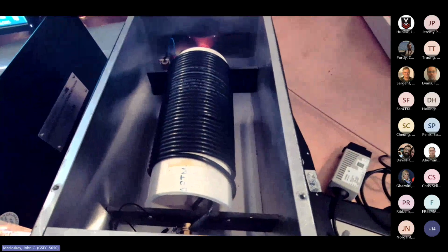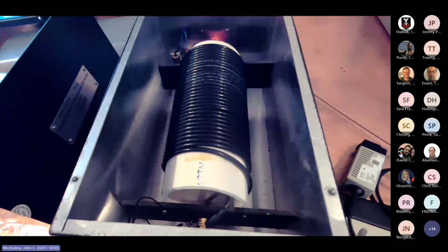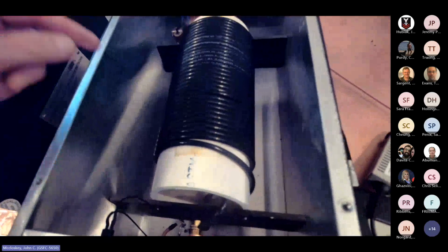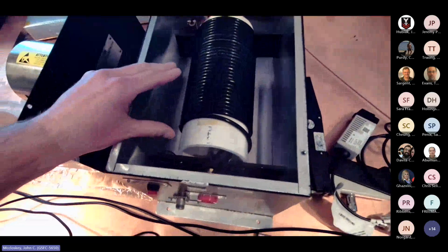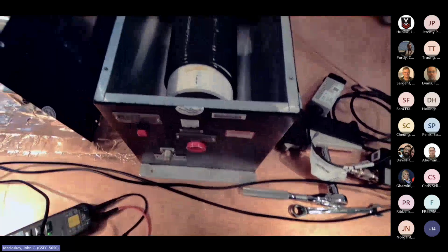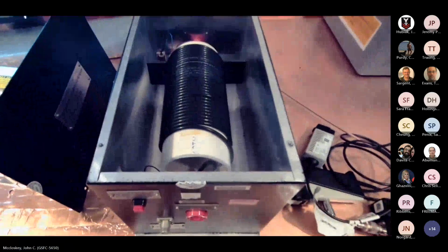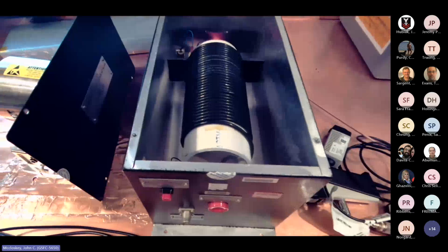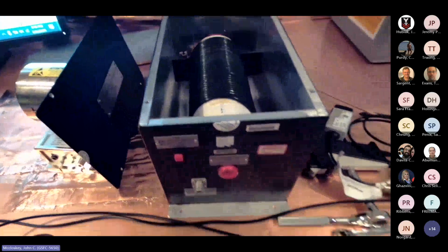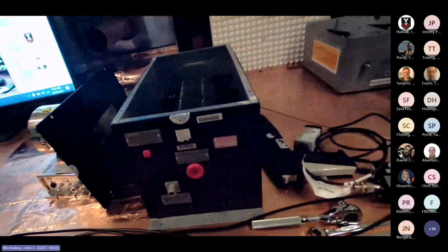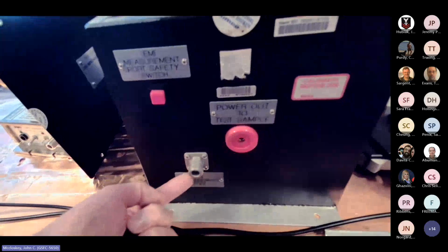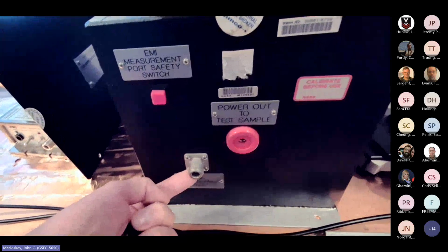So if you recall, and we'll go back and show you the schematic here in just a moment, you're running your power lead through the inductor, but then the 50 ohm input impedance of your measurement device will provide that 50 ohm shunt impedance across the inductor at high frequency. So it will asymptote at that 50 ohms. But that's a crucial part of understanding how these LISNs work and how they're meant to be hooked up. If you don't hook anything up to this port, you're not getting that 50 ohm shunt at high frequencies.